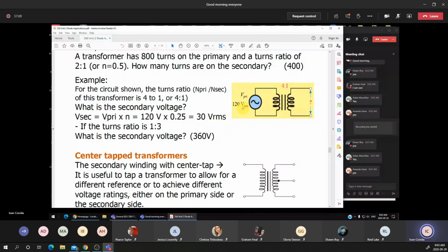That RMS comes from the input voltage. Now, suppose that I'm changing the ratio of this transformer, and it becomes a step-up transformer. In the first example, you notice that's a step-down transformer because the secondary voltage is less than the primary voltage. It means that the voltage in the secondary is always less than the input voltage on the primary.